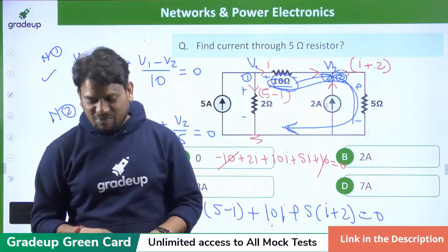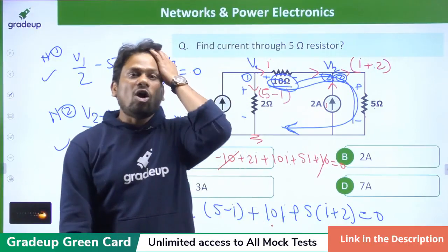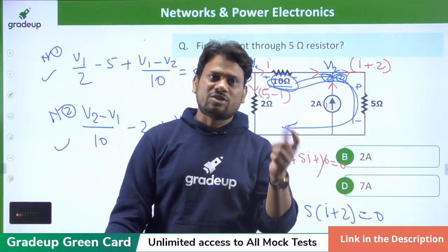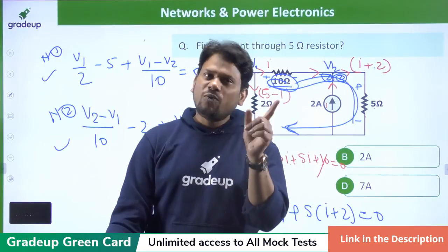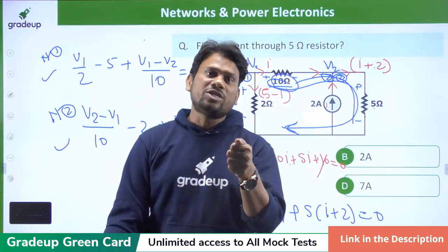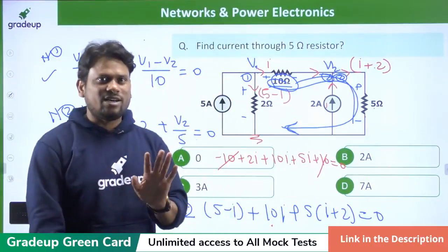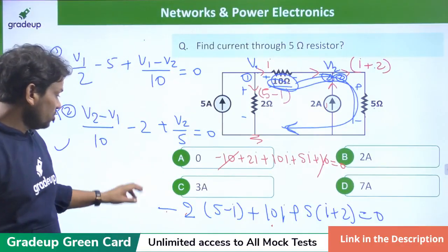Shivam Rana, for that type of question we require some time. To block high voltage, we have to introduce an extra layer, that is nothing but the N plus layer. So what is the main purpose of the N plus layer in a power diode? It is nothing but to sustain high voltage. Just keep that in mind.